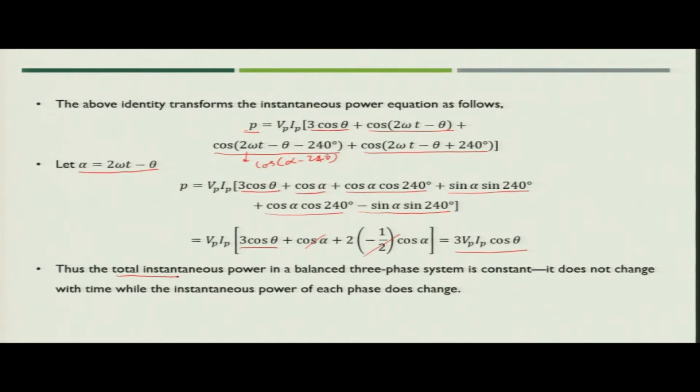You can observe that total instantaneous power in a balanced 3 phase system is constant. That means, there is no time factor coming in this particular expression. So, even though the instantaneous power of each phase will change with respect to time, the 3 phase power will remain constant.